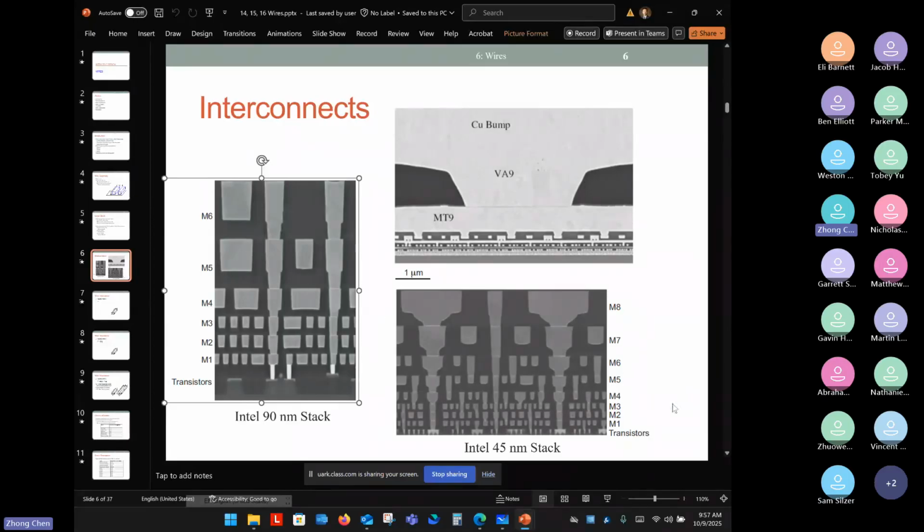So you have to know what kind of metal you are using. In the modern 45 nanometer process, you will see more metal stacking, so the copper bond is going to be even bigger. There's some design rule. You may find out there's no active circuit that can be put underneath the bond, because the copper creates a lot of mechanical stress.